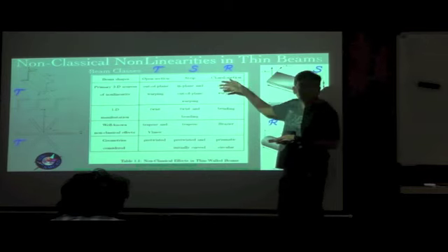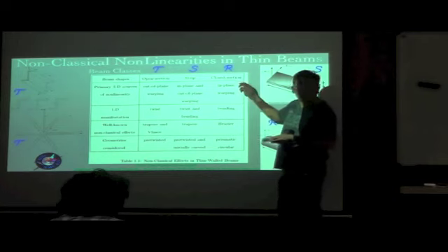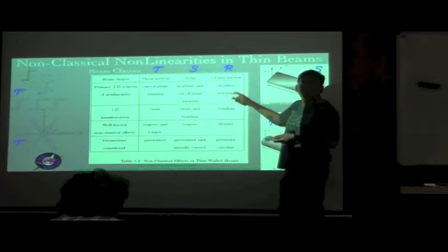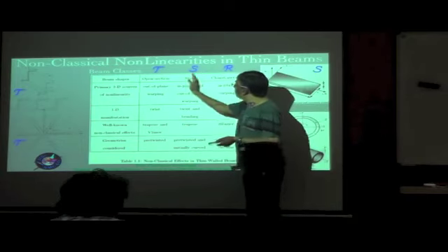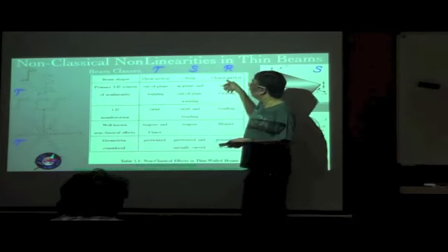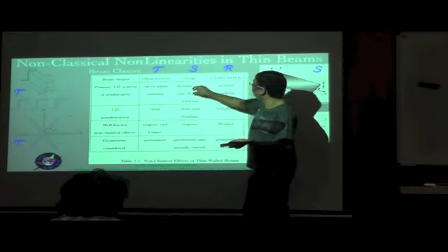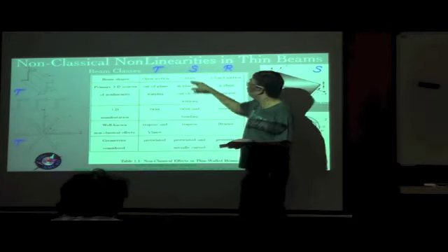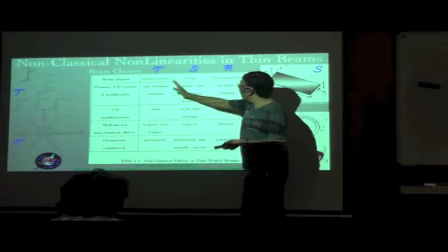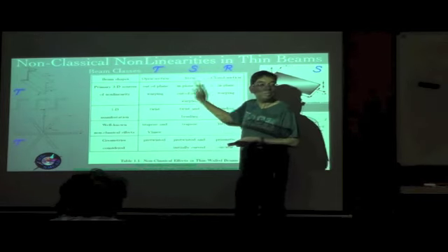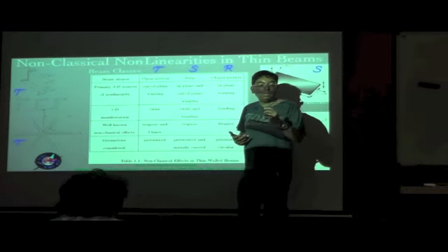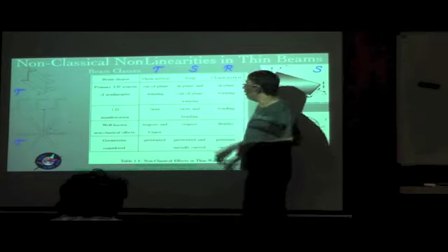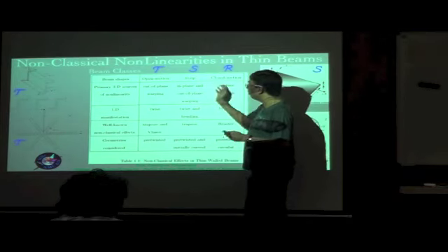But here we are focusing on the nonlinearities, and the nonlinearity example is the Brazier effect, and that is also governed by in-plane warping, in other words, W2 and W3 components. That is the warping along the X2 and X3 directions. Now the strip is a combination of both. It has the in-plane warping from the closed cross section and the out-of-plane warping from the open cross section, and it acts somewhat like a borderline situation between these, because a strip you cannot really think of either as an open cross section or as a closed cross section, even though it is thin. So in that sense it is some kind of borderline situation.